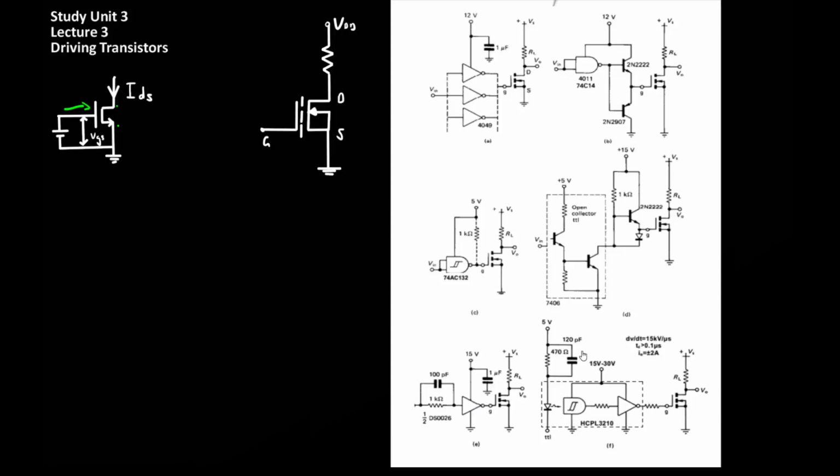In example F, the switching circuit, or the circuit which controls the state of the power MOSFET, is electrically decoupled from the switching circuit itself. In this example, there is an optical interface between the switching voltage rail and the power voltage rail.